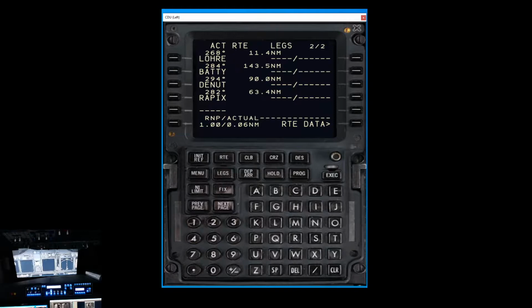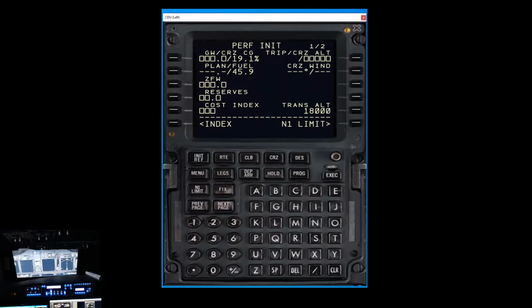The next thing we want to do is start putting in the cruising altitude, the speed at which we're travelling, our V1 and our VR speeds. So if we go now to our INIT REF page here, it'll come up to our performance profile, and we just go again off the SimBrief flight plan. This is all calculated for you, so you can enter it in. I'll show indications in overlays.